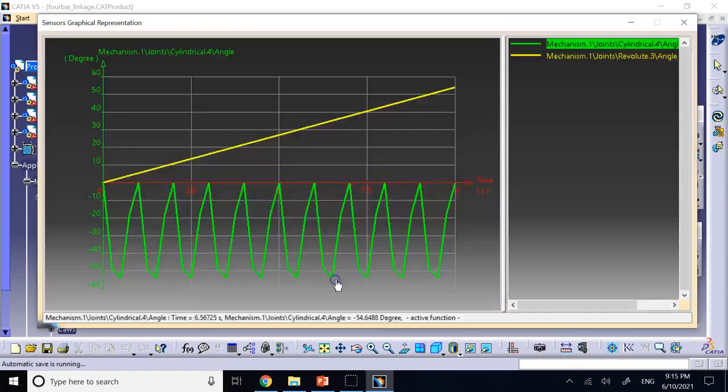And now when you run it, those sensors will be populated with new data. And now when you click on graphics, your results are way more visible and nicer, meaningful. And you clearly can see, although the input angle versus time is changing linearly as it should, the output angle versus time is definitely not constant, not changing linearly. And even if you look at the angular acceleration of that, nothing is constant for the output.